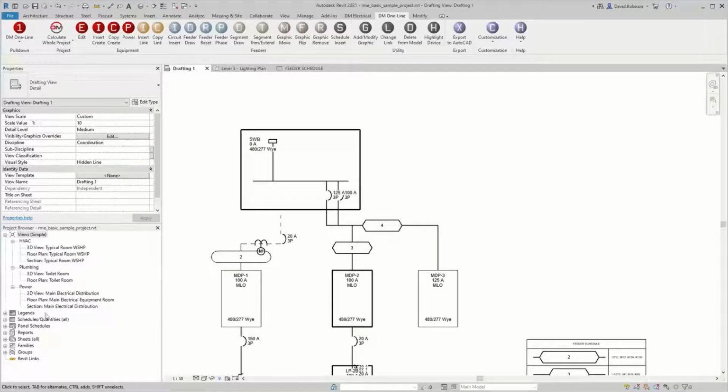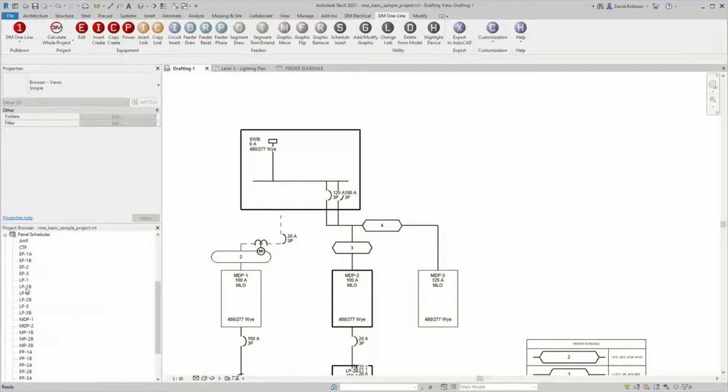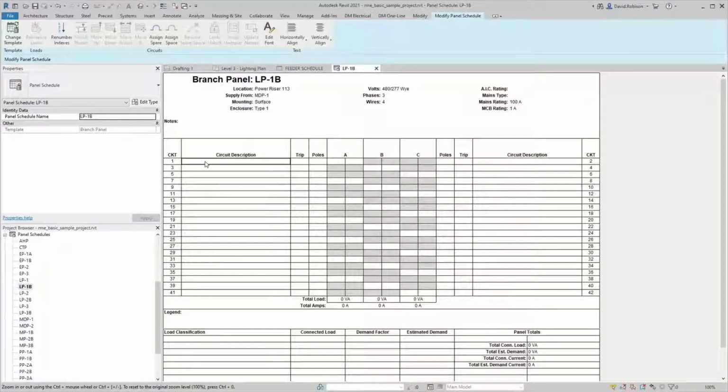The problem that we have with that is if you go to a panel schedule and you come in here and you assign this as a space, or you assign it as a spare, it kind of gets this orangey thing. These orangey things are very, very different from the other things and how Revit is internally dealing with them. So we have not quite figured out how to crack the code to know that you've even got these in there. Revit is not very forthcoming on that. So if we put those in there, I'm pretty sure we can't see them at all.